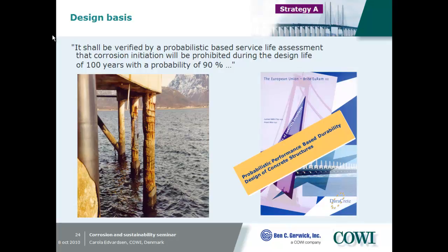We had to verify this service life by a probabilistic approach, and the limit state was that after 100 years only 10% risk is allowed for corrosion initiation. At this project, COWI worked as the main consultant together with DEWO, who was the main contractor for the project.